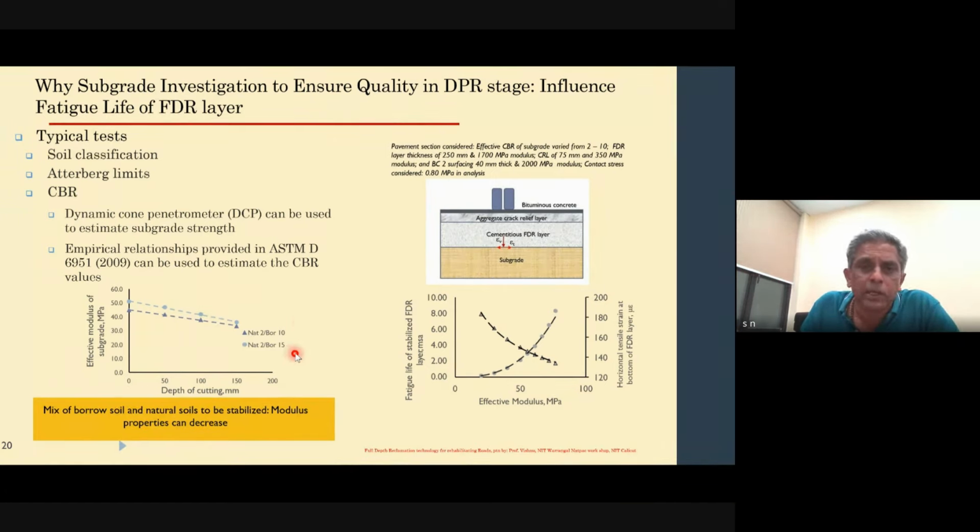Now, in terms of cylindrical samples, correction factors may be applied, because the ideally recommended one is a cube. So if you are using a cylinder instead, there is going to be a difference in the strength. So the correction factor is going to be added, which is there in most of the codes, depending on the size of the cylinders that you are actually preparing. Now with the same material, you prepare your flexural strength beams as well. Then in terms of requirements, compressive strength requirement at 7 days is approximately 4.5 megapascals.